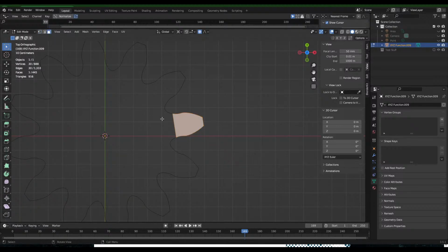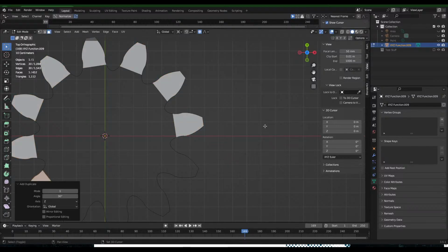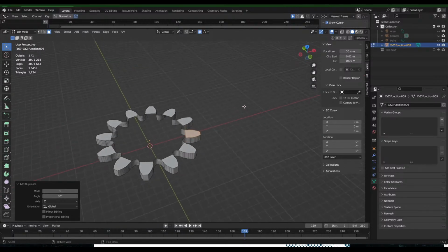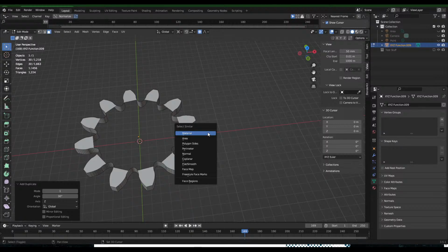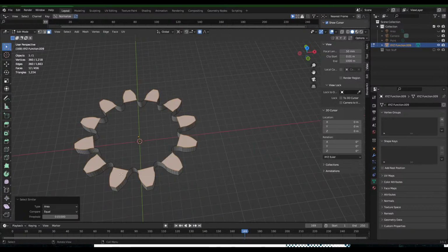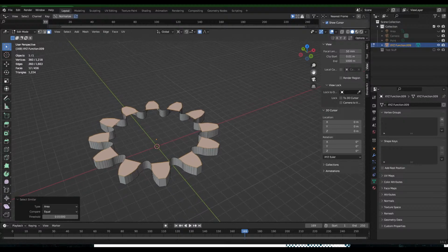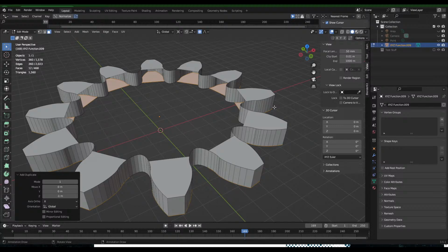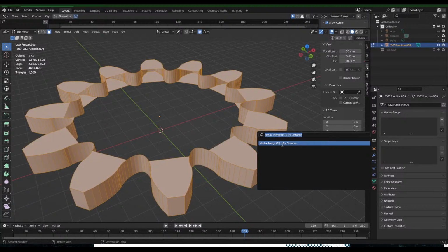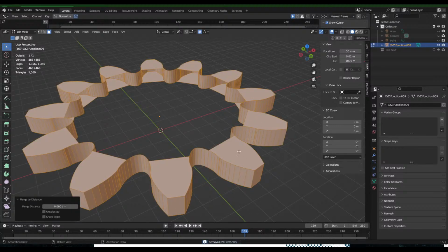If we go to face select, select that again, Shift D, R, Z, and 30. Shift R to repeat the function, and there's the top of all of our teeth. If we now do Shift G and select similar by area, it's going to select all of those faces. We'll go ahead and Shift D to duplicate, Z and -1. Now those are attached to the bottom. Now if we select everything, F3, merge by distance, it's now all connected.